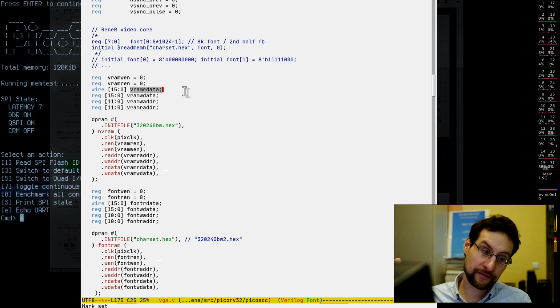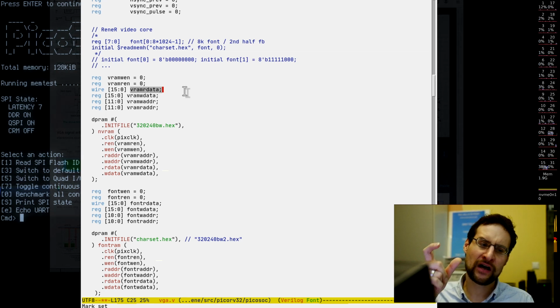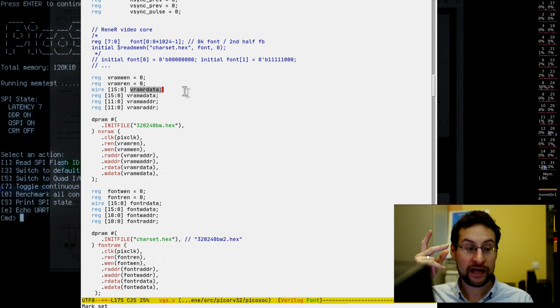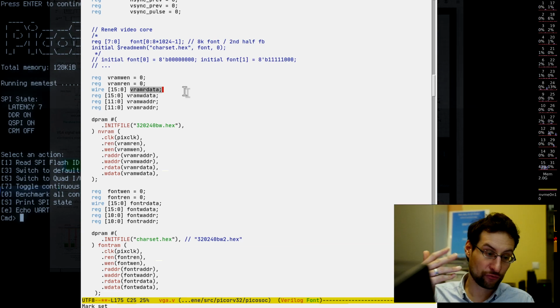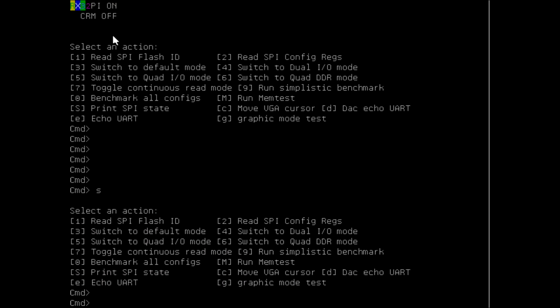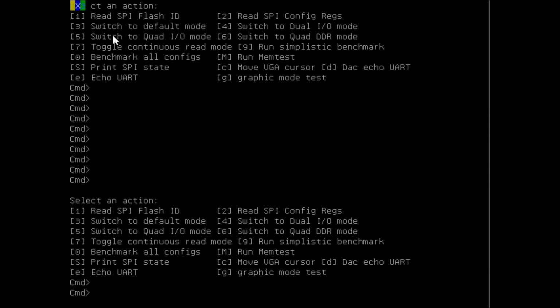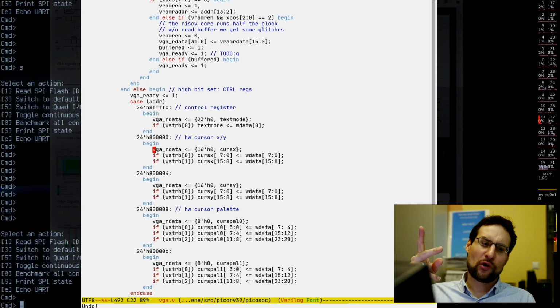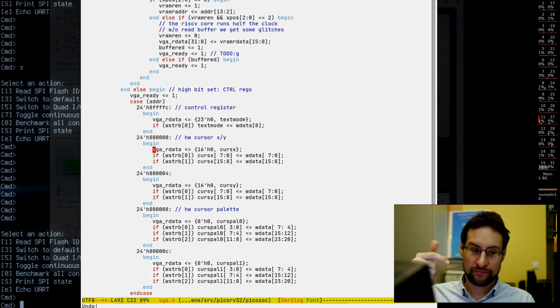So right now writing to the frame buffer is quite okay. However, the RISC-V CPU is potentially writing 32 bits, of which half are wasted. So even the write performance, if you wanted to, we could double, because right now we can only access for reading half of the time. So reading is relatively slow, here for scrolling pixels, this is relatively slow. And so the write performance could be doubled with a 32-bit memory bus.